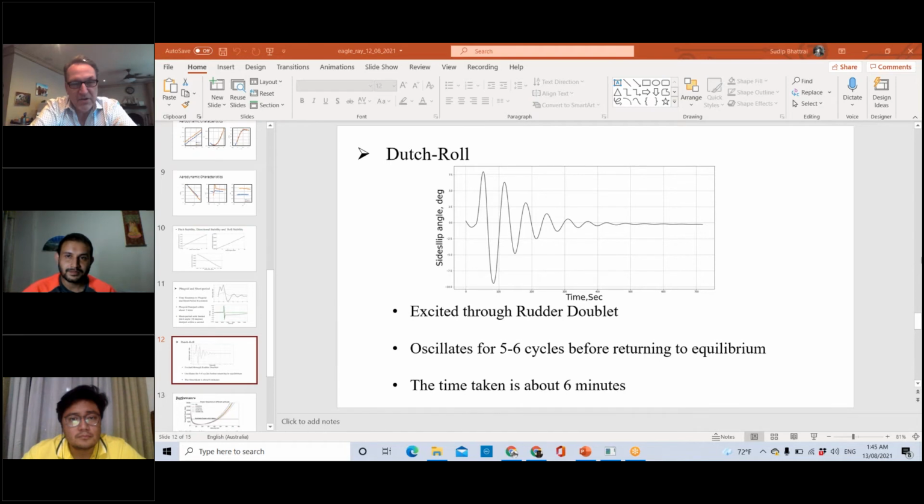So tell me about the down winglets. They're cool because you can integrate landing gear and things like that. Was the up versus down winglet part of the gain, the lift to drag ratio improvement that you saw? Was that playing much of a role? Yeah, we did test both wingtips down and up, but we didn't really see much of a difference in the lift to drag ratio because of the wingtips.